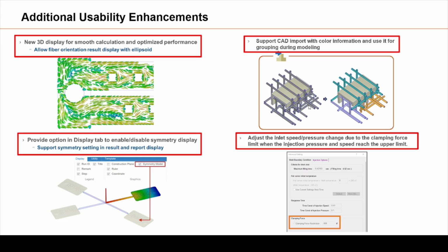When importing a CAD geometry, if that CAD geometry had a color representation in your CAD system, that color representation will now be maintained coming into Moldex3D. And so instead of Moldex3D just importing as a bunch of uncolored, unattributed objects, now a user-defined setting will be applied automatically to group these objects based on their color. You can change or clear the colors from the model tree. This will help to organize that information more effectively.